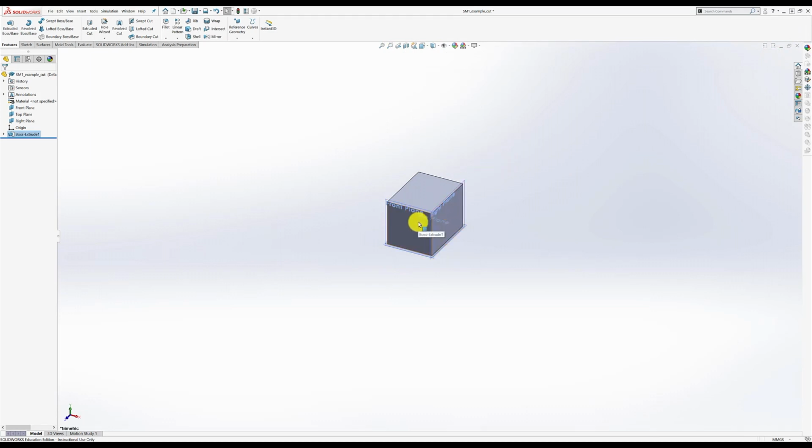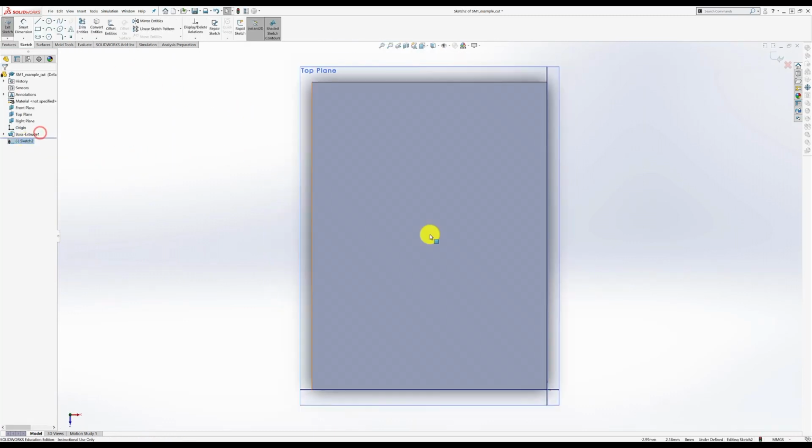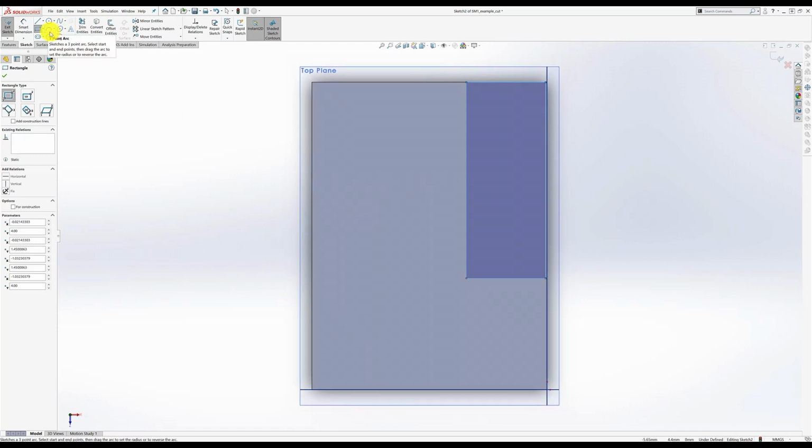Now I'm going to create the shape via cutting. So I can cut from the top plane upward or from this face downward. I'll start with just cutting at this top face here and downward. So I'm going to create myself a cut. I'm going to choose the plane that I want to make the cut on. I'm going to take a look at that plane from a normal view, and I'm going to place my cut approximately where I want it to be. And while I'm at it, I'm going to do this at the same time on the other side.